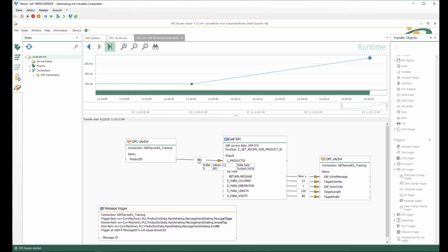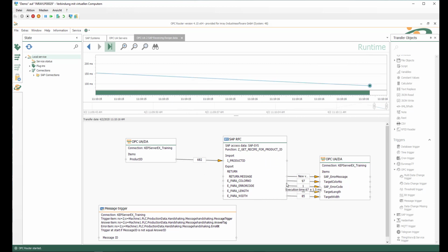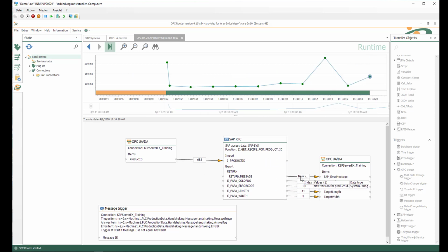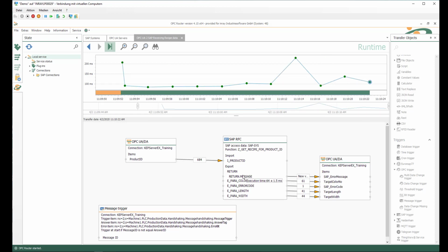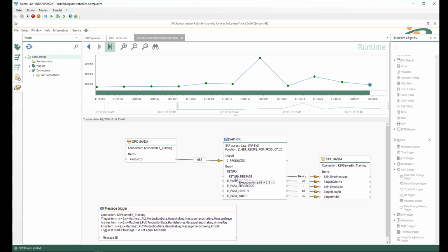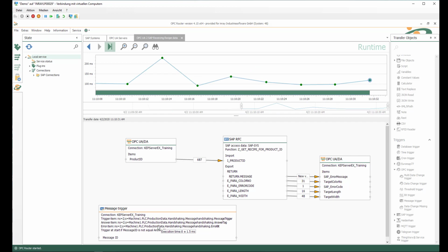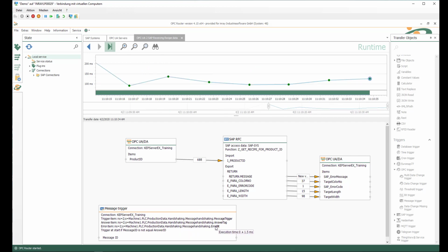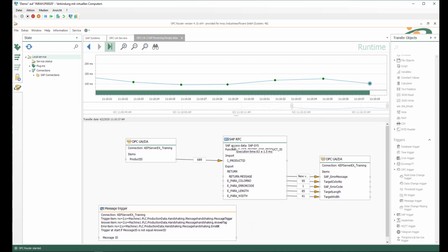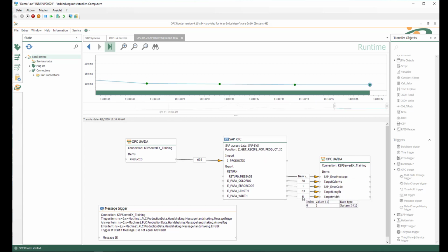And below, you see the connection and you see the values that are written to the SAP system, and you get the error message back if one is available during the return parameter. This error return is different to the error bit that is set in the message trigger, because this error bit would be set to true if, for example, the SAP function cannot be called, or this SAP function throws an error itself, so you don't get the result values. And you have the information on the PLC. If everything is okay, the bit will be set with the value 0 or false.